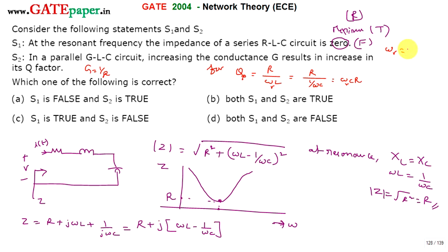Whether it is a series or parallel RLC circuit, it is the same, 1/√(LC). Substitute this in place of ωR in either equation and you get the expression for quality factor, R times the square root of C/L. This is the quality factor of the parallel RLC circuit.